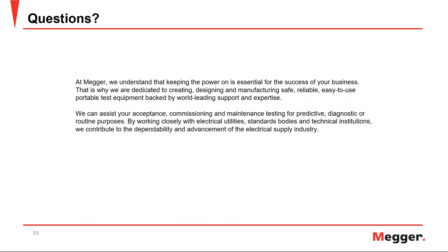So if your value decreases, it also means that you have a problem. It hasn't gone completely negative, but power factor improving by itself is also a concern. So make sure that your values are either staying the same, or at least not decreasing, because that's an indication of surface contamination.